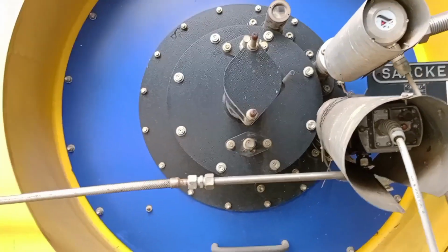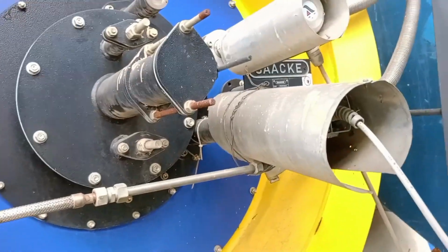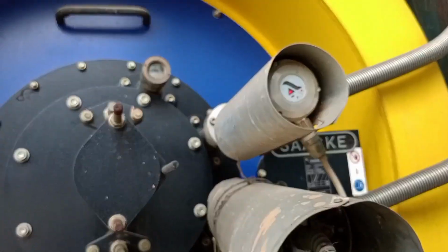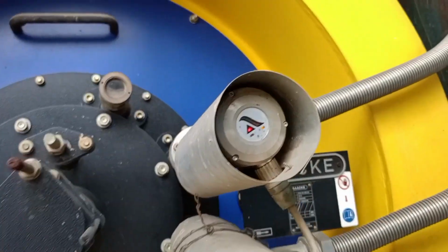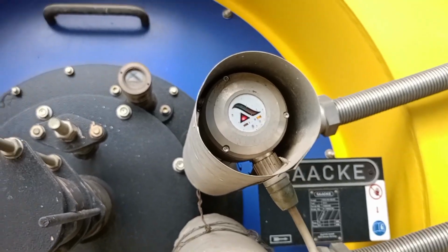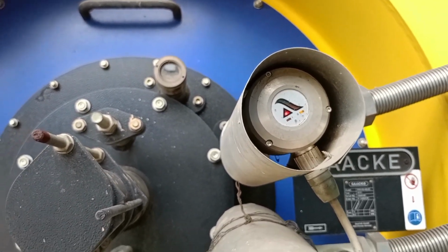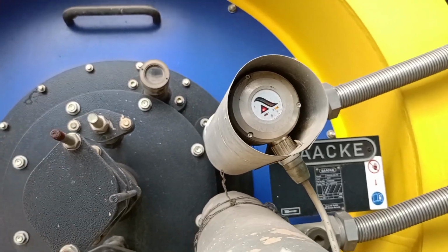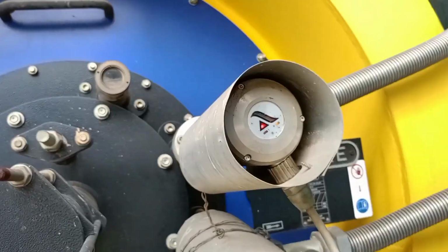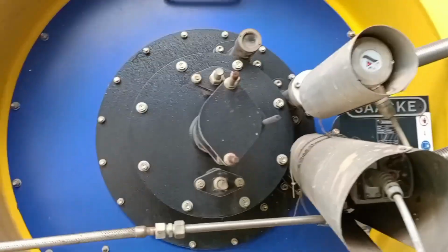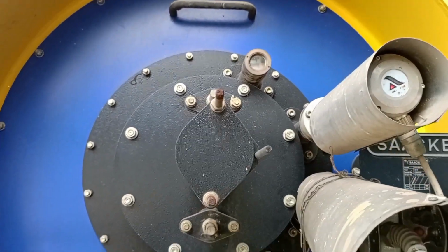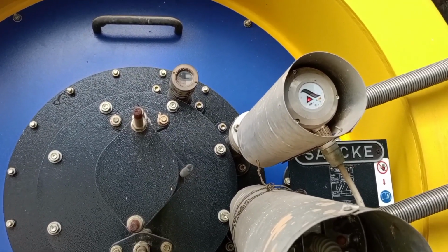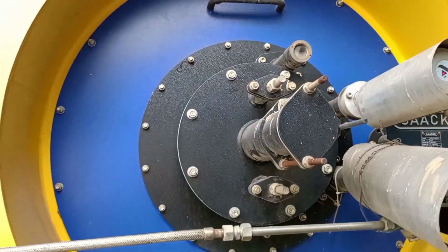is likely maintained. And when fire is created inside this chamber, then here is a flame detector. This flame detector detects the fire, and here you can see now the stop condition, and here is no fire. So when fire is created inside the boiler, this is green color and the circuit is closed. If for any reason the fire inside the boiler stops, then this flame detector will detect it and at the same time stop the boiler burner.